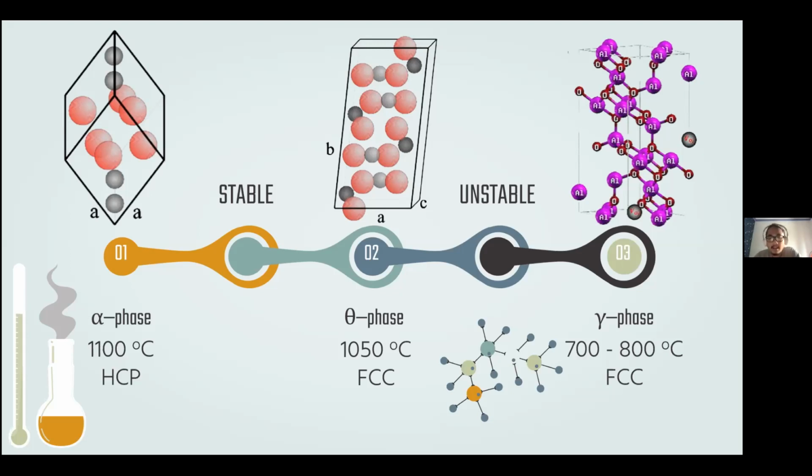And then the alpha phase is formed completely at around 1000 degrees Celsius and is thermodynamically stable. It is utilized as a coating layer to hinder or even prevent any surface degradation. The enhancement is achieved through the embedment of alpha phase aluminum oxide into the surface of the component, thus providing good mechanical properties, chemical inertness, thermal stability, and other crucial properties.